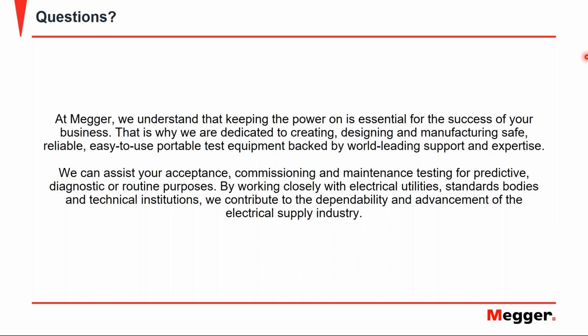It's important to understand that whenever we connect to a cable and set it up to do partial discharge measurements, we need to have PD-free connections to accommodate the test, because we want to make sure that the sources of partial discharge that we find are valid.